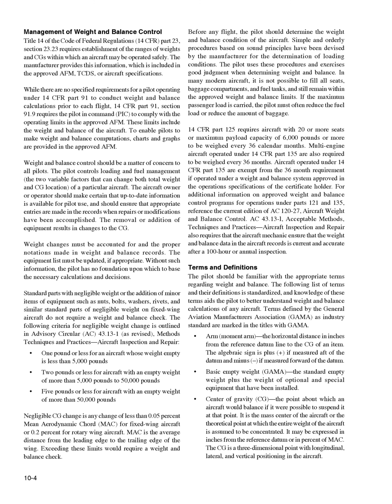For additional information on approved weight and balance control programs for operations under Parts 121 and 135, reference the current edition of AC 120-27, Aircraft Weight and Balance Control. AC 43.13, Acceptable Methods, Techniques and Practices, Aircraft Inspection and Repair also requires that the aircraft mechanic ensure that the weight and balance data in the aircraft records is current and accurate after a 100-hour or annual inspection.